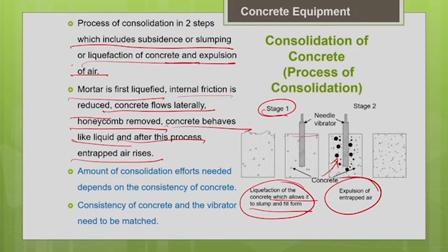As I told you earlier, how much consolidation effort you need depends upon the consistency of your concrete. For a very stiff mix, you need more consolidation because there are more chances for air entrapment. So the consistency of the concrete and the vibrator need to be matched.